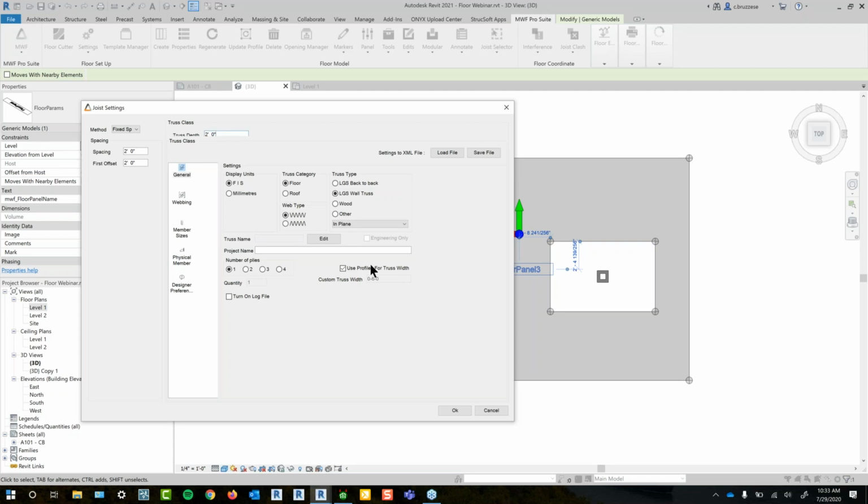But from here, if you just get those trusses spaced out correctly, the depth is correct, then you can actually go over and switch to the truss module if you want to manually modify these or maybe change out the webbing, modify them in the designer, or even run analysis on them. Then you can go ahead and switch over to the truss module.